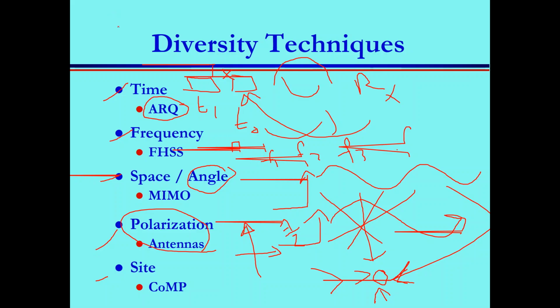Anyway, now you send your signal with vertical polarization. Yes? Now, suppose your receiver is horizontally polarized. To be received by the receiver, you must make this aligned with the horizontal so that you can induce current in your antenna.